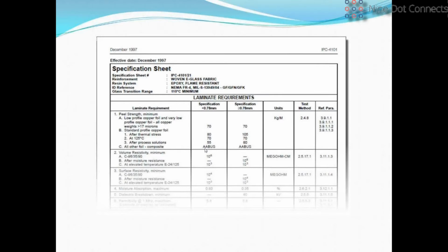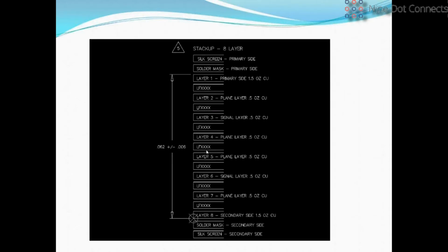One thing I'd like to make sure you understand today is that you've got to create balanced construction. The reasons are numerous, but suffice it to say that if you don't create a balanced board, your board manufacturer is not going to want to design or build that board for you. So start with the stack-up.